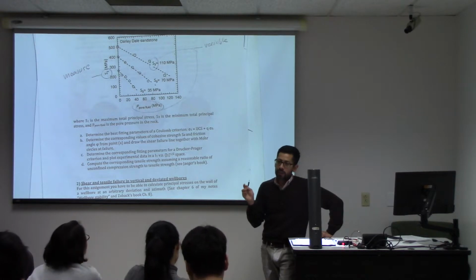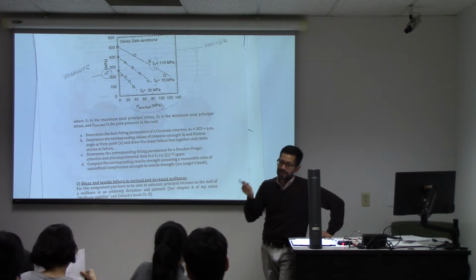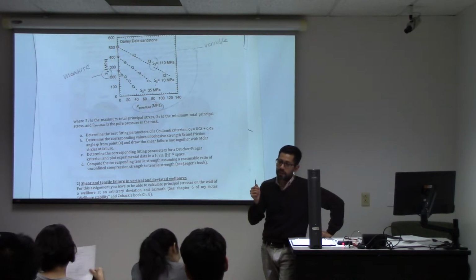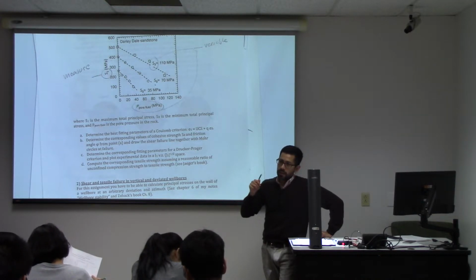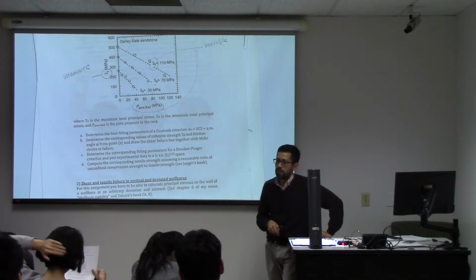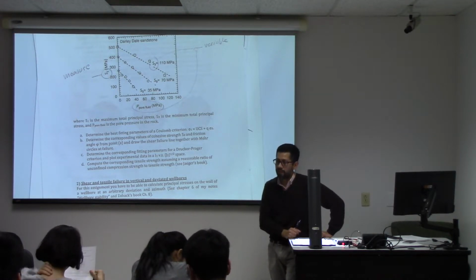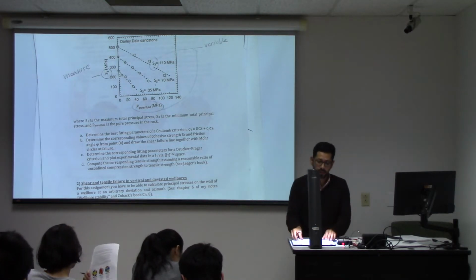But failure is usually a large strain process in which small strains may not be such a great assumption. So it turns out that most materials behave closer to Terzaghi effective stress than they do to Biot effective stress. So use Terzaghi effective stress.